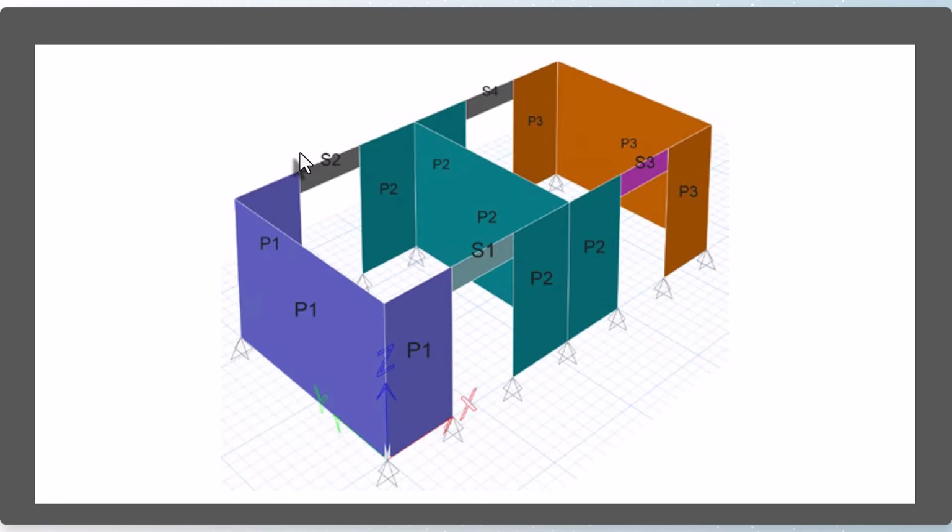This figure presents an example of a wall core with an appropriate assignment of pier and spandrel labels. The example has three different walls connected through four coupled beams. There are two C-shaped walls, P1 and P3, on each edge of the core. In the middle, there's an I-shaped wall, P2, connected to both C-shaped walls by the webs.